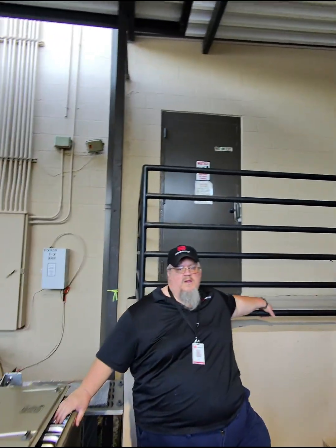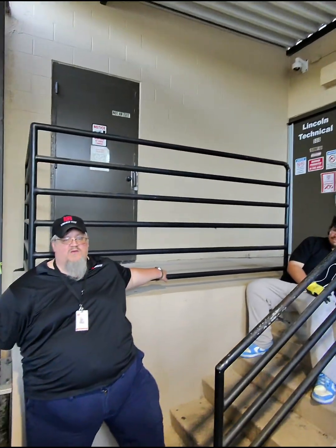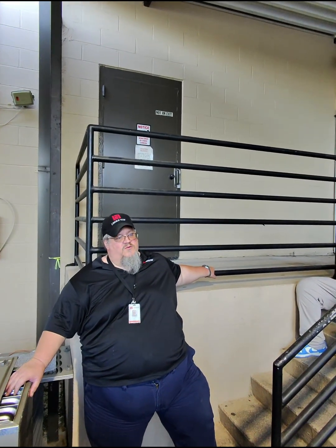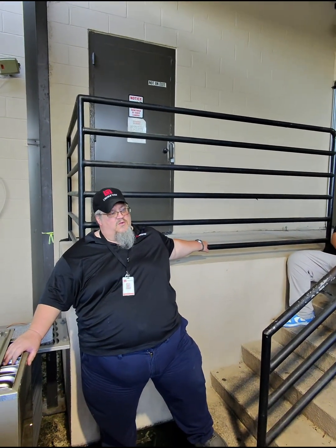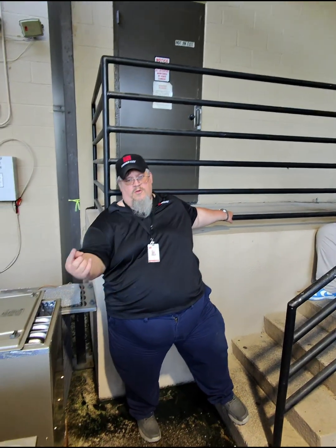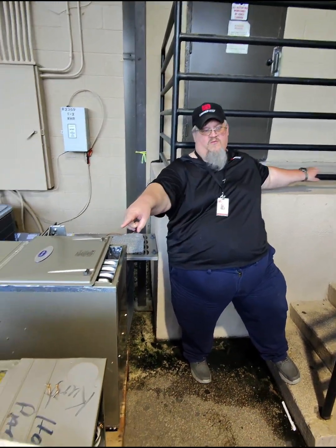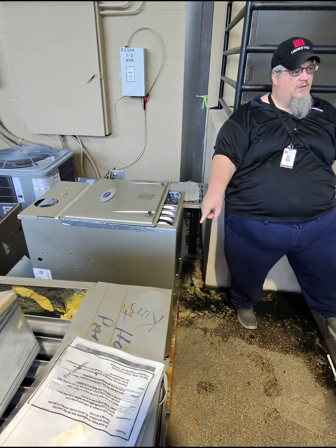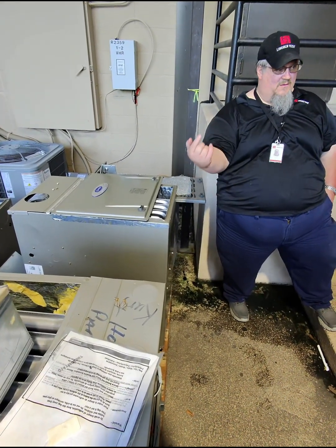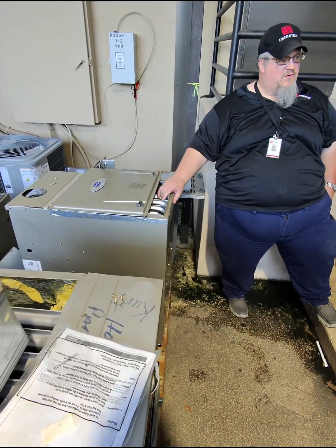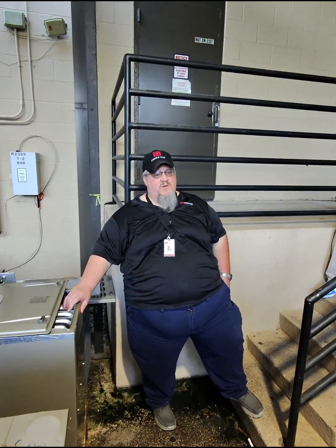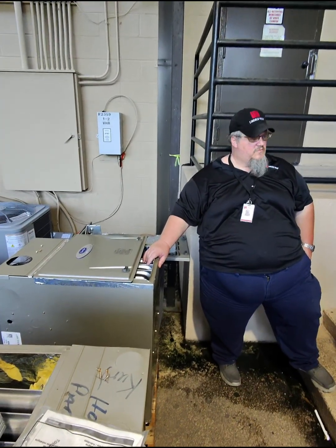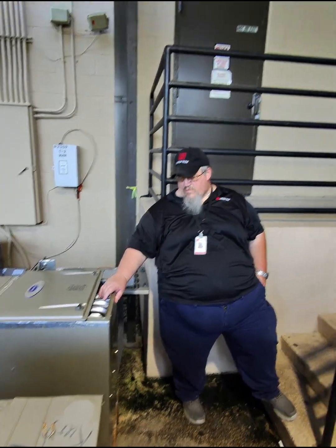If they got a lot of pets and stuff like that, they may have run the unit without filters in it. So that coil will stop up before your evaporator will stop up. Remember your evaporator's up top, but that's going to stop up first because that's your first coil that you come to. So remember, that can cause you problems.